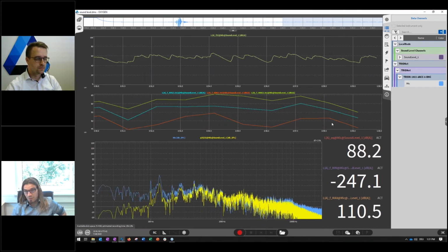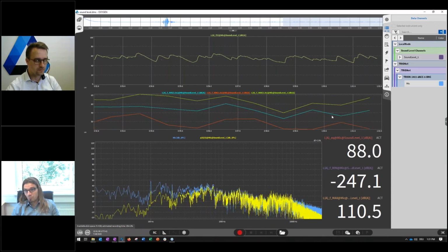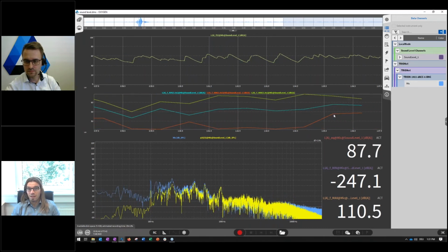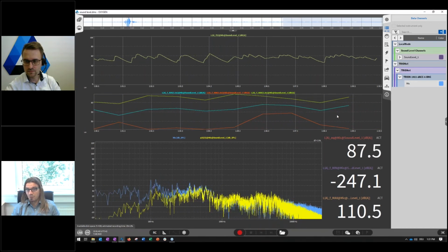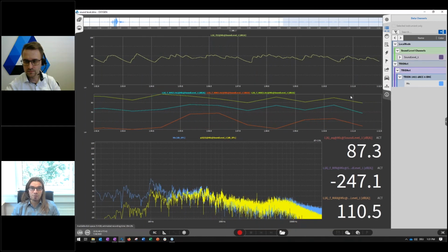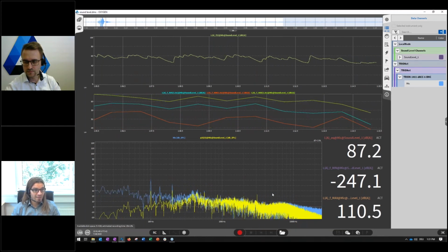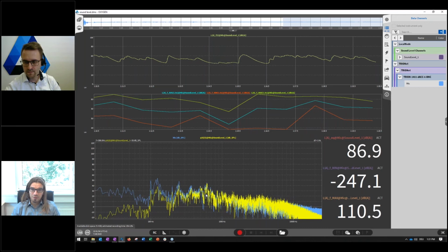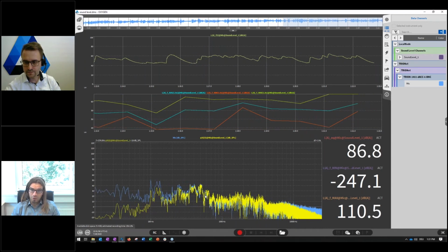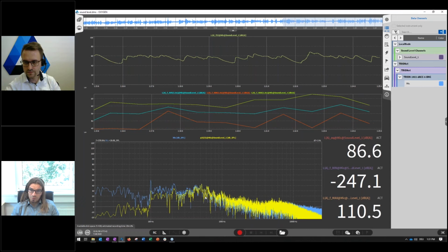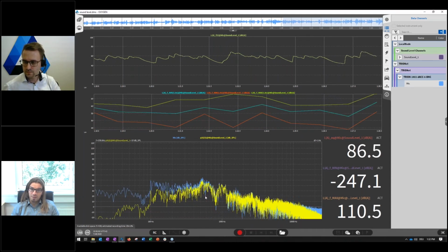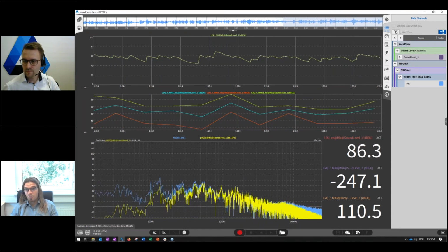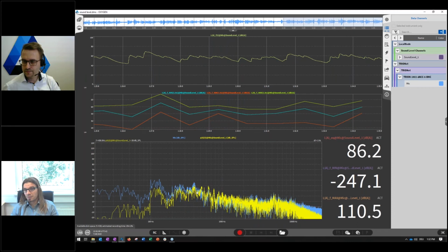And you also have the possibility for a time-dependent sound pressure log. So you can update the minimum, the maximum, and the average sound pressure level for a time interval, for example, of 1 second, like you can see it here. And additionally, I would like to show you that you can also determine the frequency-weighted raw sound pressure still in Pascal, which can then be used for an order analysis, in case you don't necessarily want to determine an order analysis for the structure-borne noise, which is acquired by an accelerometer.